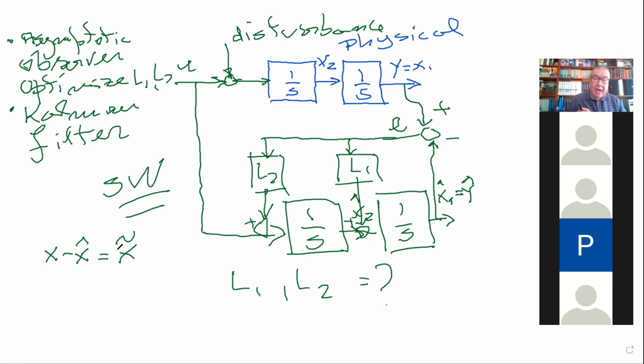Okay. Now, we have a similar situation here. We have how to design a controller. And if I do state feedback, I will place the poles where I want. For which class of systems is this possible? So you have the criteria of controllability. One thing is to design the controller. The other thing is to know whether the controller exists, if it is possible to be designed.